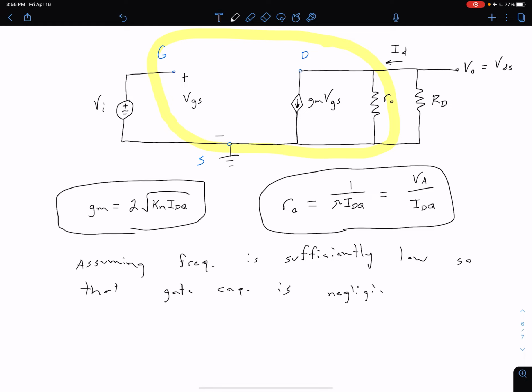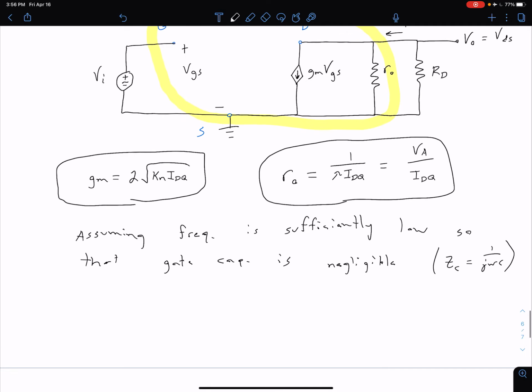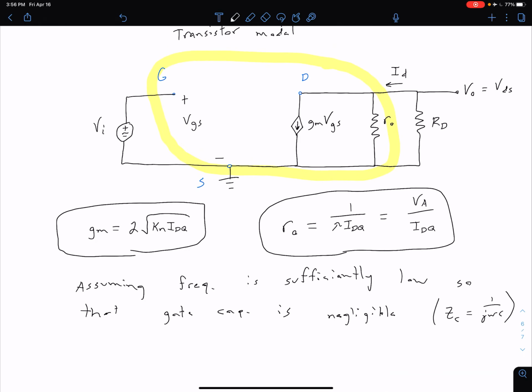So negligible. And keep in mind the impedance for a capacitor is equal to 1 over j omega C, or negative j over omega C. And as we saw in some of our lab activities, if we have transients, if we have switching going on, that can lead to issues because for a DC, a capacitor is going to appear like an open circuit, but as we have really quick changes, that appears like a high frequency, so we can have relatively large amounts of current flowing in no time unless we have appropriate circuitry sort of leading into our gate.